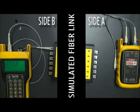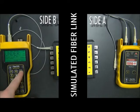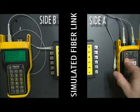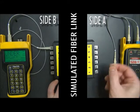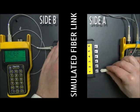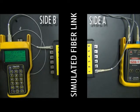But what we're going to do, actually, most people will store 850 nanometers first. So let's switch the wavelengths to 850 on this side, and then again on 850 on this side, making sure that the indicator LED is solid. We want to be taking measurements in continuous wave. So what we do is we take the light source and plug it into its side. So we find the 850 nanometer cable and we plug it in. Okay, as you can see, we have a loss reading on the screen once we plug in.